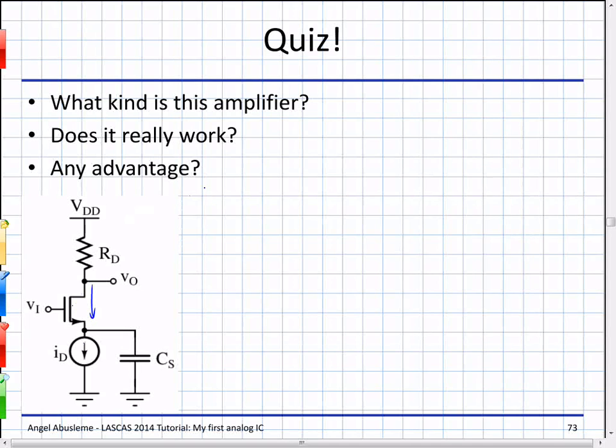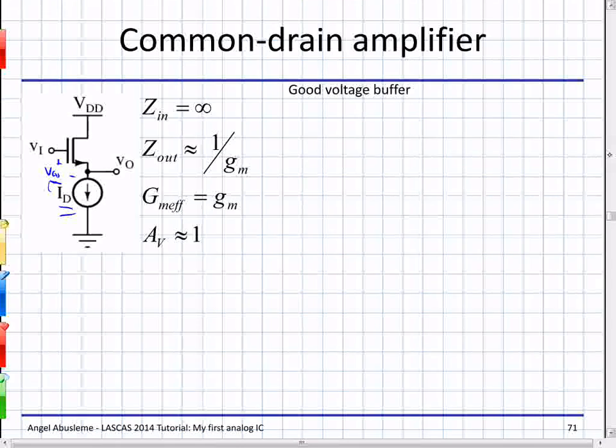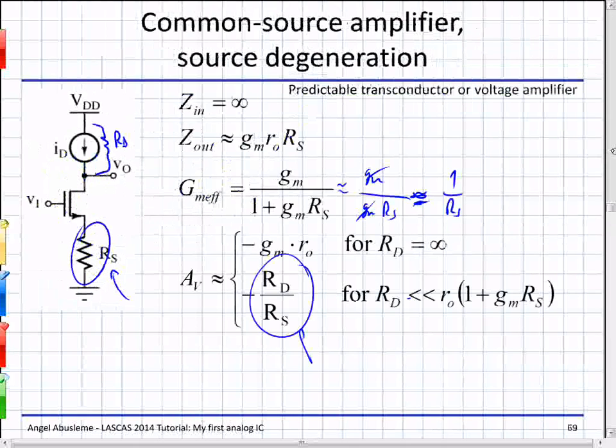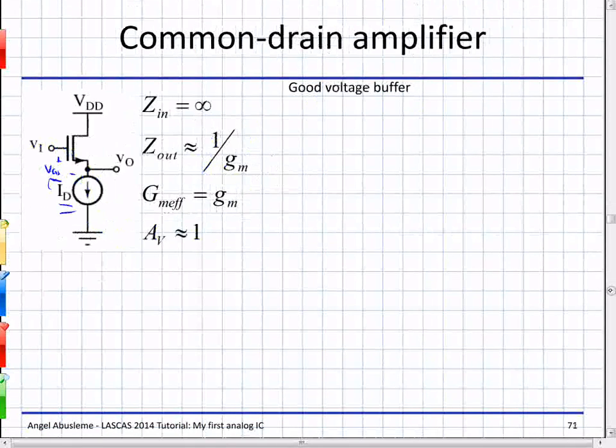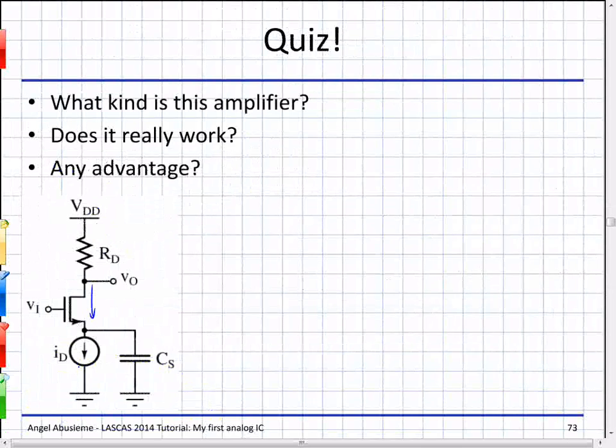Well, basically, this amplifier is the same as this one here. But in this case, we need to provide a very precise VGS to have this transistor in the operation region we need. In this case, this current source will make sure the current here is ID. And VGS will be anything to make sure that this ID is in this transistor.